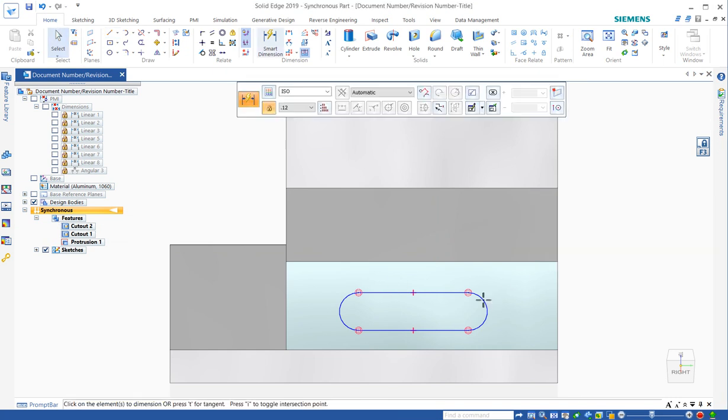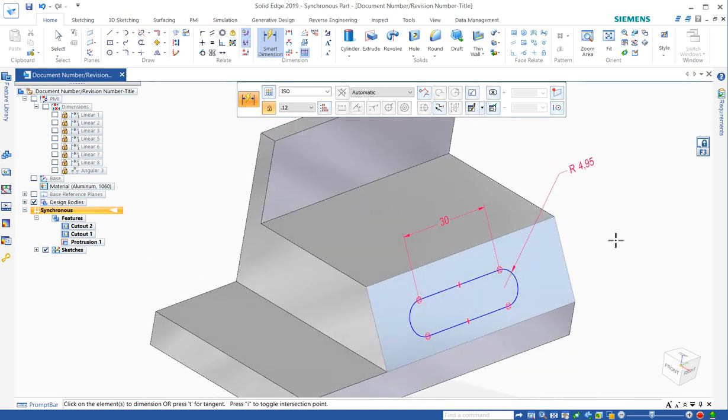You might not notice it until you start to place dimensions, and the dimensions will appear to be vertical instead of readable. You'll have to lie down on your desk to read your dimensions, and that would be an indication that your plane orientation is probably 90 degrees off, and that is easy to do, but that's how the software does it.